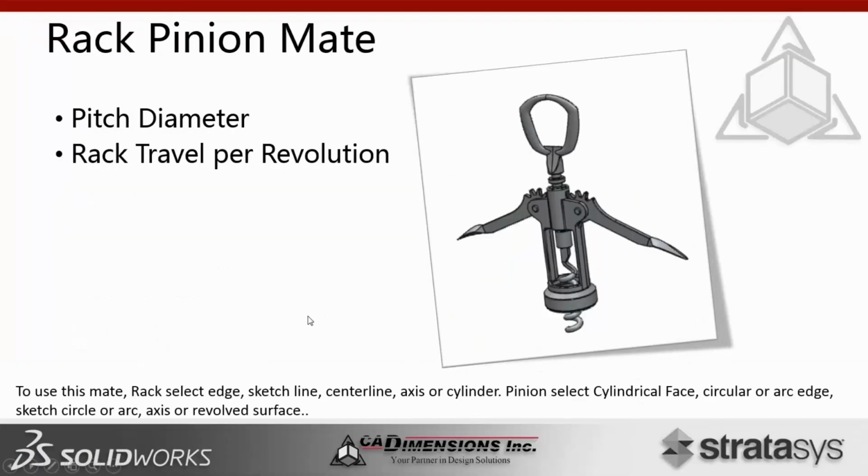Continuing on. A rack and pinion mate. Rack and pinion allows us to take a translational movement and tie it to a rotational movement. We can define that using a pitch diameter and then a rack travel per revolution.